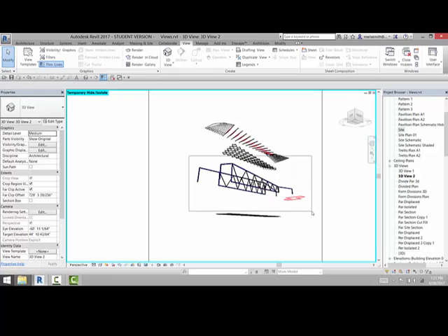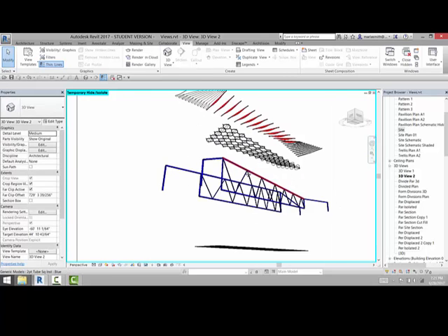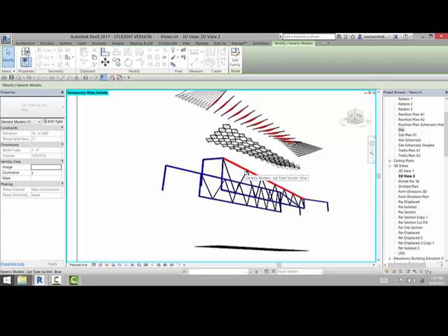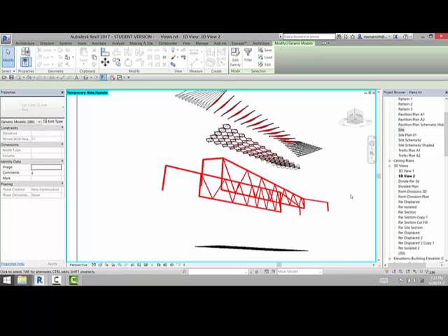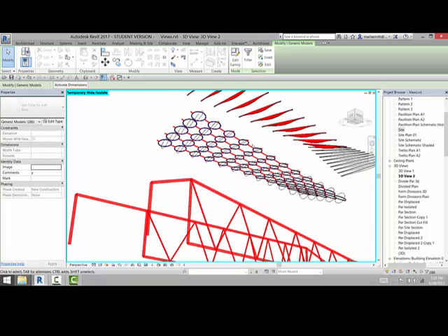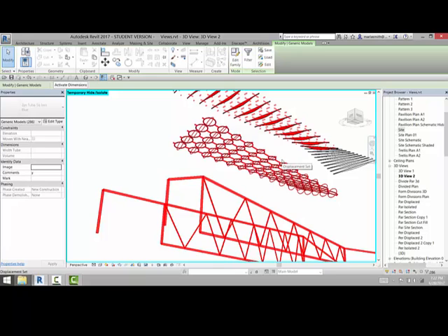I do want to come in and select this guy. Let's select this guy and right click and go to select all instances in entire project. So it selects all those. Unfortunately, it selects all of the circles up there because they have the same family in them, and it doesn't allow me to sort of blanket get rid of that selection.